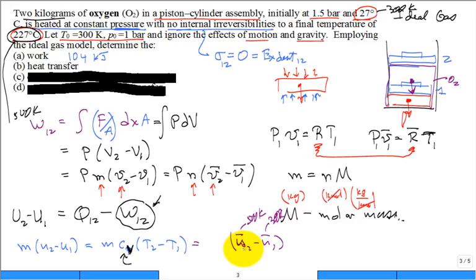What's it say for the units on that U bar? Kilojoules per kilomole. So do I multiply by M or multiply by N? And you can go back and forth between M and N. No problem. I have the molar mass of oxygen. What's the molar mass of oxygen? 16 and 16, roughly 32. You want more digits? Look it up in the table. But it may be 32.00 if my memory is correct.